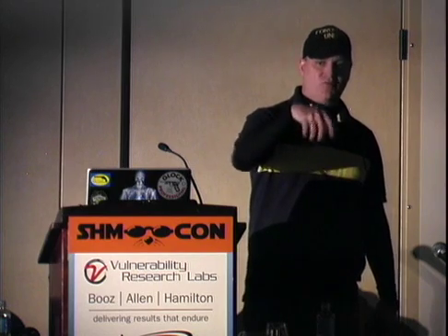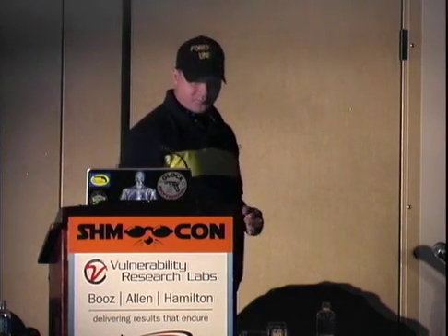Now, the exception to this is that some of the newer Seagate and Western Digital hard drives that are now in little mini towers and standing up on their end, and you jiggle the table and they go boom, right? What happens is that the platters are so heavy, in a lot of cases the spindle will break free, and the spindle inside the drive will not turn anymore at all. So if you open up the drive and you're not able to turn it at all, and the platters don't spin at all, then your motor is seized, and that's a more advanced replacement at that point in time. But if it does turn, and you can break the head free, you will probably be able to read your data and do okay.